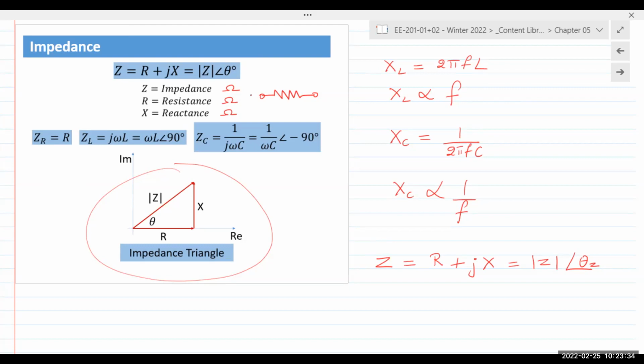The coil is an inductor, or electrically is represented as an inductor. Headphones typically have 32 ohms of impedance. Speakers that you buy off the shelf typically have 8 ohms impedance. That, of course, is not constant. The impedance changes depending on the frequency. If the frequency is high, the impedance is going to increase. If the frequency is low, the impedance is going to decrease. So 32 ohms and 8 ohms are a typical average value.